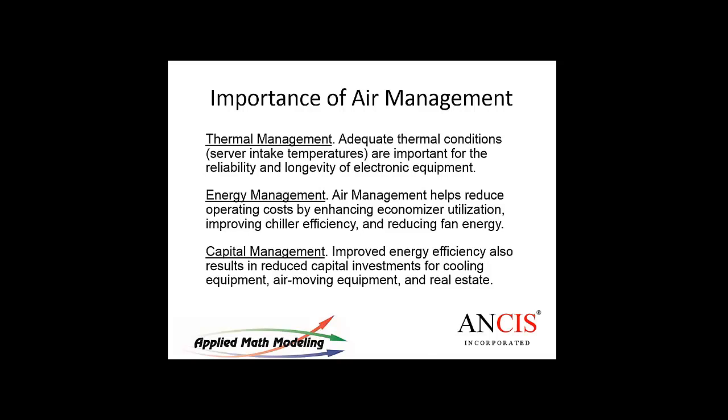So do you want to cover this one as well, importance of air management? Yeah, absolutely. Traditionally, I think air management was about thermal management, and we've explained that. But also, of course, it's well connected with energy management. Like I said, if the return temperature is depressed because of bypass air, the chiller will not work as efficiently as designed. But maybe the most important today is capital management.